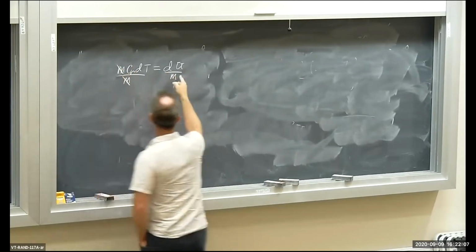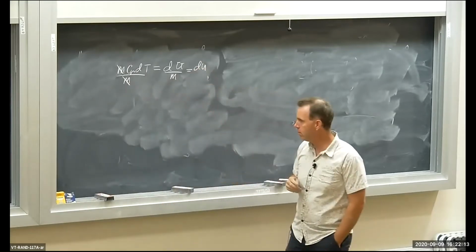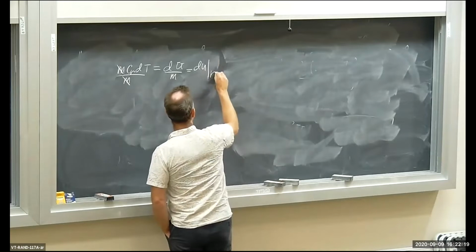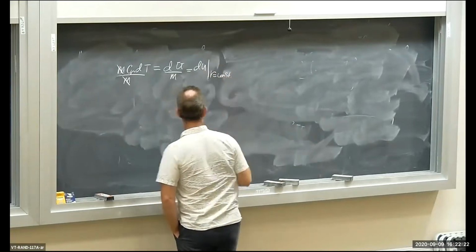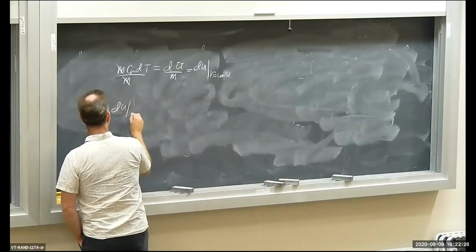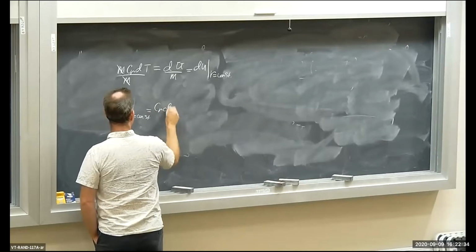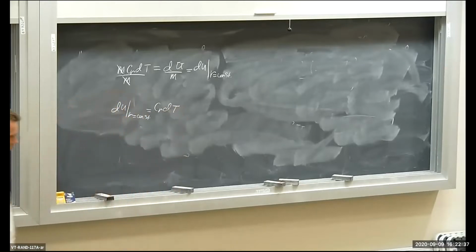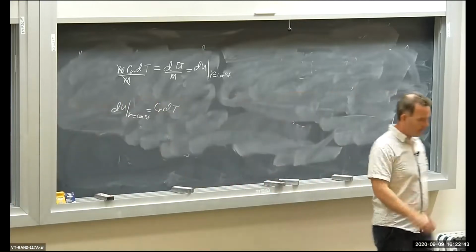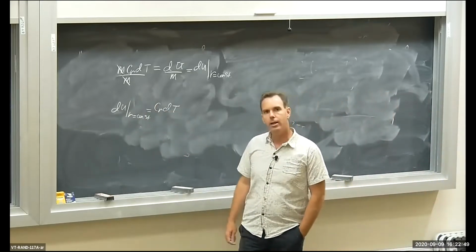The mass cancels out here, and this becomes specific internal energy. Now remember, this was for a constant volume process, so I do want to say here, volume equals constant, isochoric process. Let me flip the equation and write down what I have. dU for a constant volume process is equal to Cv dT. You give me the change in temperature and the specific heat, Cv, and I'll give you the change in internal energy. This is for a differential process.